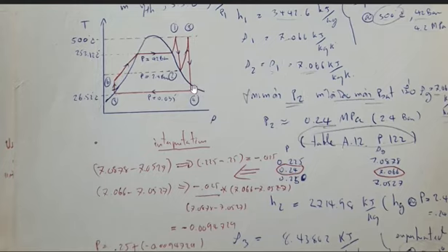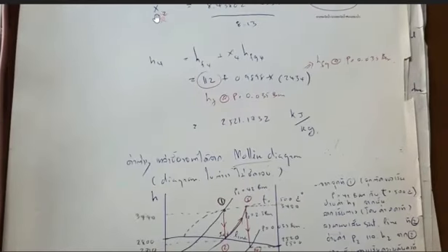And I said along this line, it will be 100% vapor. So this is very close to this line. So as we found that the X value here is equal to 0.9898, which is almost 1 or almost 100% vapor. When we get the value X, we can substitute in this equation for enthalpy.